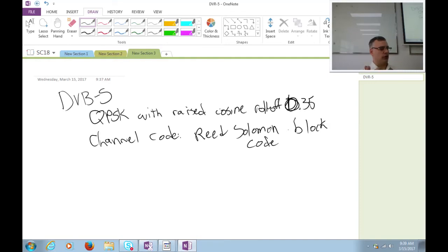And it's usually some sort of combinatorial algebraic operation on the transmitted bits to give you one or more error detection bits. The simplest one is the parity bit check, right? You send a bunch of ones and zeros, and you exclusive OR them all together, right? And that basically gives you a 1 or a 0.